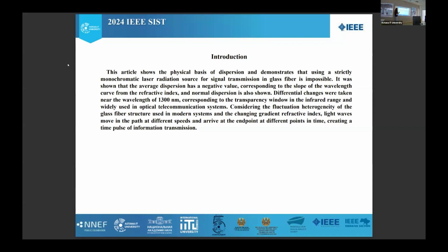The welding and joints of the optical fiber, which accompany the technical cycle of operation, lead to constant layering, coupling, and cassettes, inevitably leading to increased losses of radiation into the environment. In addition, the modulated transmitted signal in the glass core and shell will be accompanied by Rayleigh scattering caused by the heterogeneity of the density of the material. Both of these facts affect the choice of the wavelength of infrared radiation that will be used to transmit information.